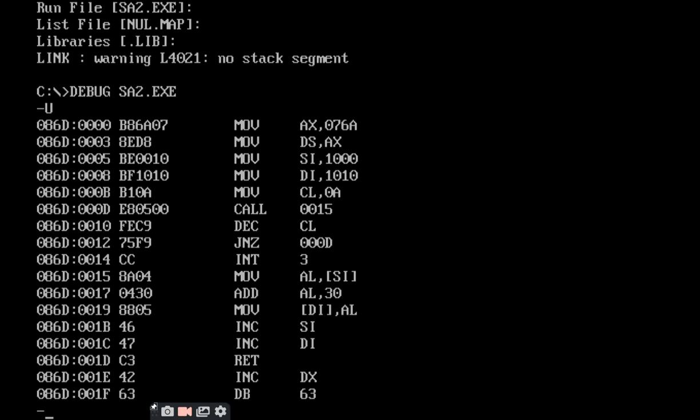Okay. So the first column represents the segment address, the second column represents your offset address, then B86A07. So this column is there, right? That column is known as your opcode, then followed with mnemonic, the operation, and followed with operands. So this is what is known as the opcode sheet. So this you have to represent in your records. That depends how we are going to do.